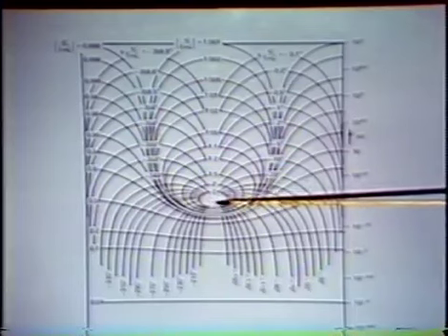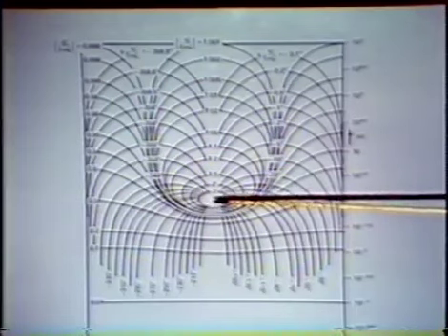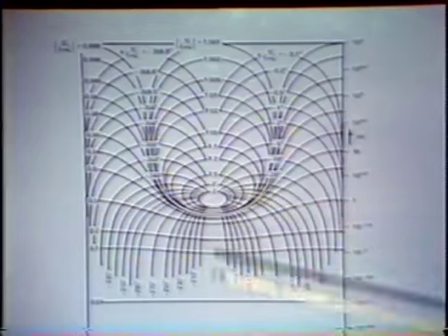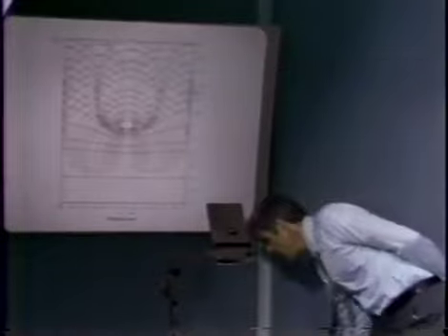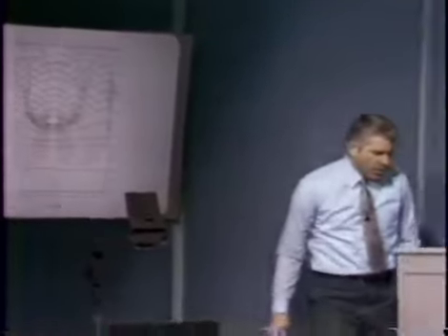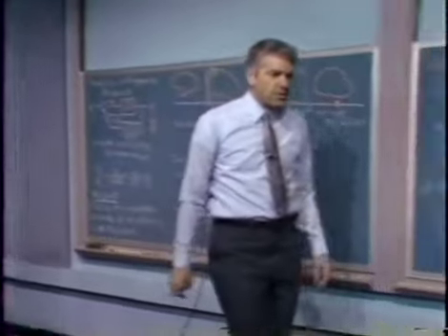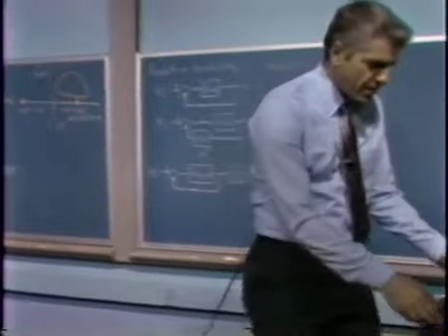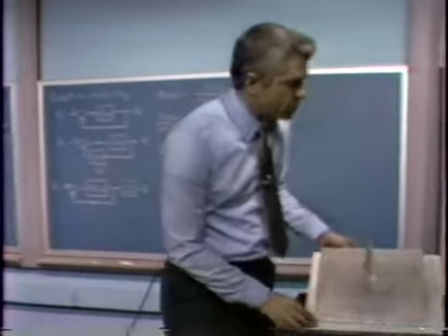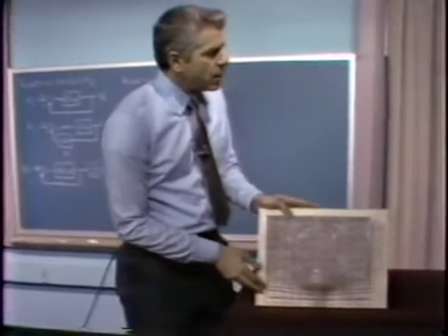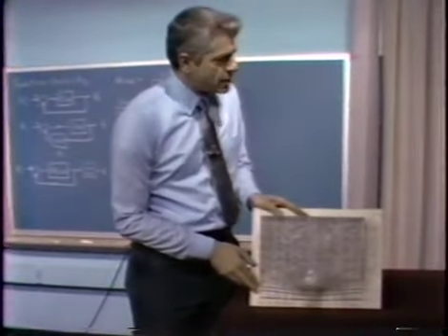There'd be little ellipses in here with progressively larger magnitudes as we got closer and closer to the minus 1 point. A very nice way to look at this is to look at a three-dimensional presentation of the Nichols chart, something that we might call Mount Nichols, for example. And here we have exactly that situation.